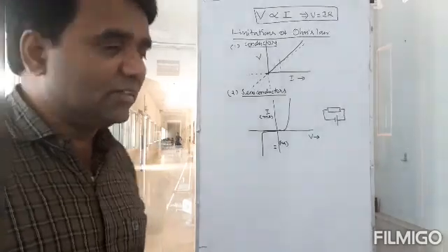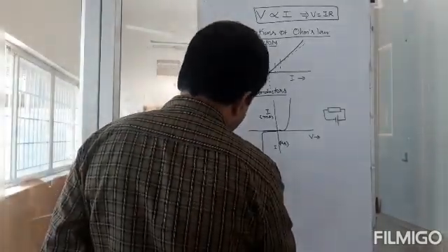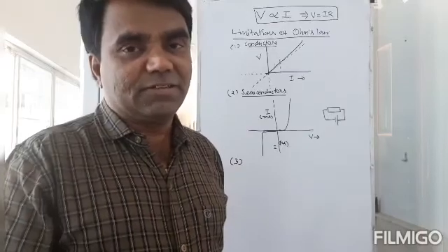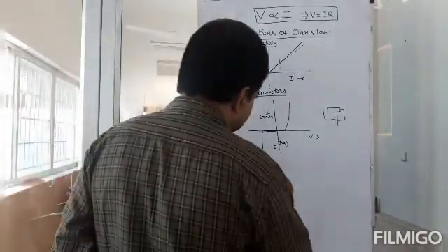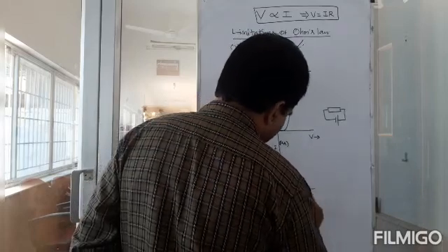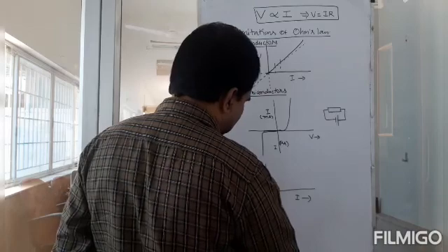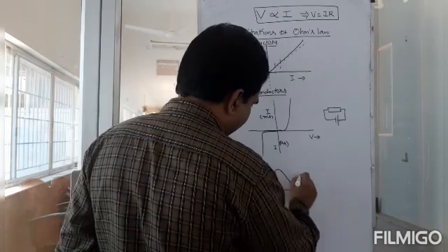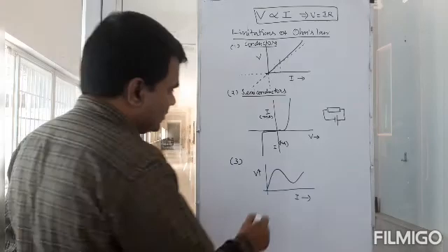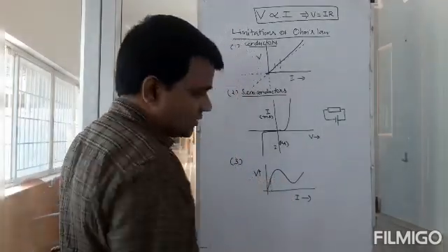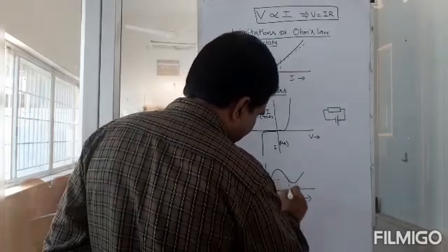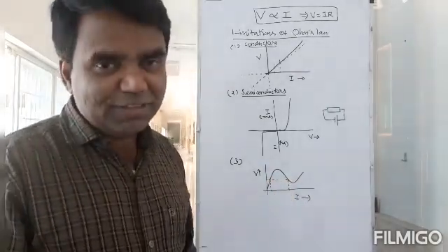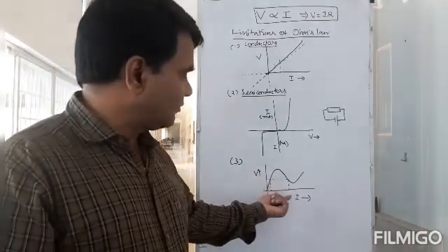Then there are certain other types of conductors like gallium arsenide, where you don't have a unique voltage for an amount of current. See, that graph looks something like this. You keep increasing the current, and when you keep measuring the voltage here, notice that it is like this. You get a curve like this. Notice, for this voltage, you get this current. And then for the same voltage here, you get this current. So you have a dual value of current for the same amount of voltage.